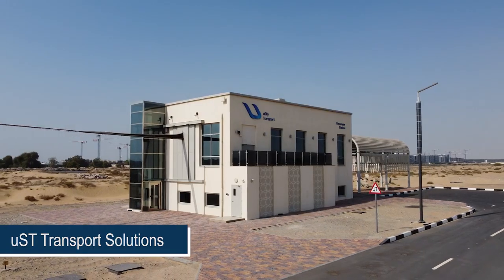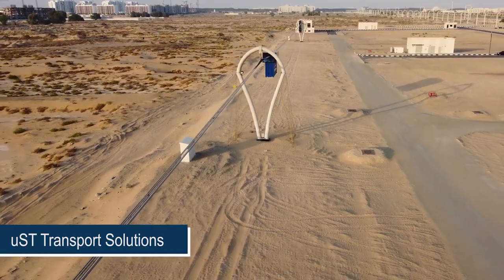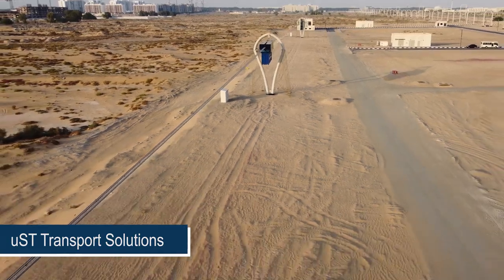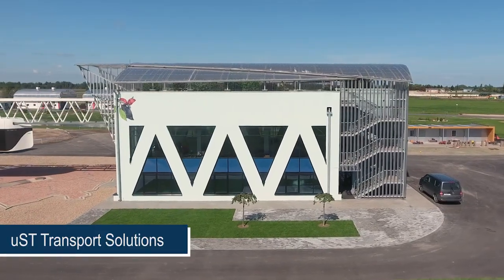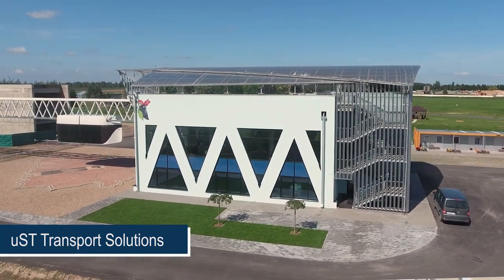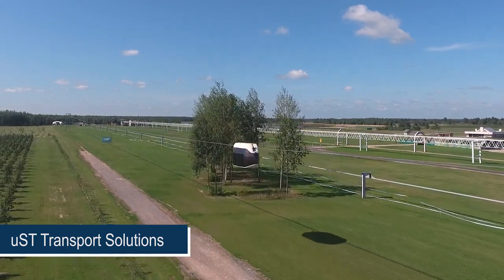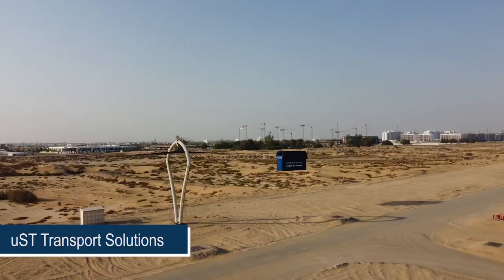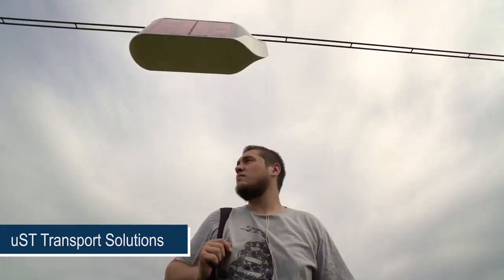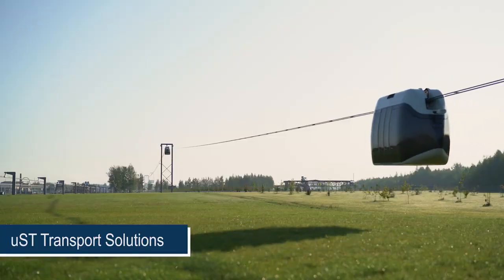The horizontal load from stretching is taken by anchor supports installed at a distance of up to 5 kilometers from each other. They can be combined with buildings for various purposes, including passenger stations and cargo terminals, as well as commercial institutions. The span between intermediate supports reaches 2 kilometers, which makes it possible to effectively overcome water barriers, pass over residential areas, mountain gorges, transport, or energy communications.